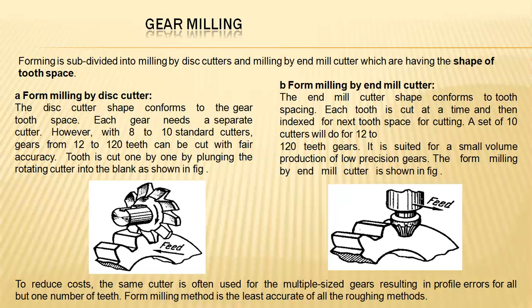Nominally, for example, 8 to 10 standard cutters can cut gears from 12 to 120 teeth, with better accuracy, maintaining the perfect accuracy as per the drawing.